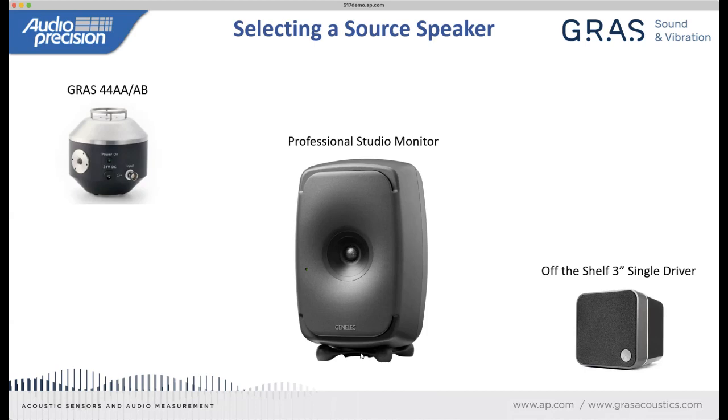When we're just looking for a speaker to generate test signals over a broad range, the considerations are really bandwidth, over what frequency range we want to generate those signals, the signal levels we need to generate, and then, frankly, what our budget is.